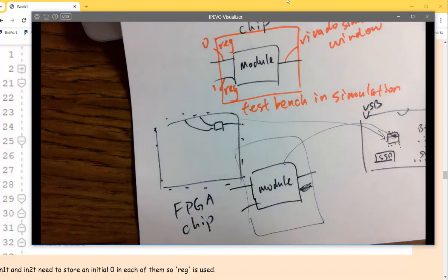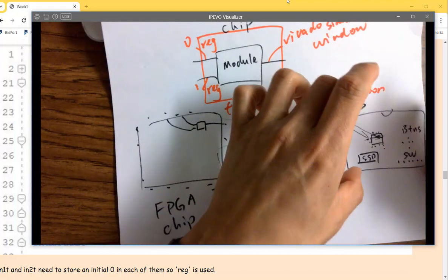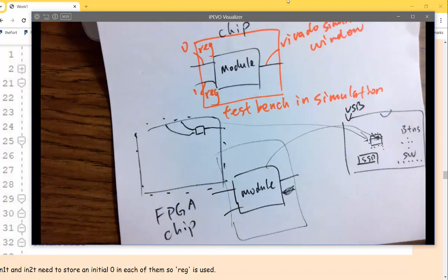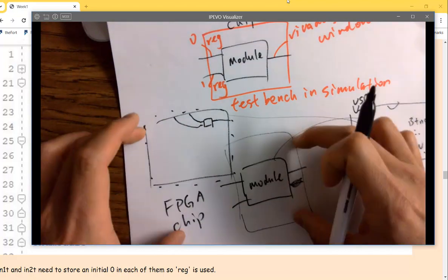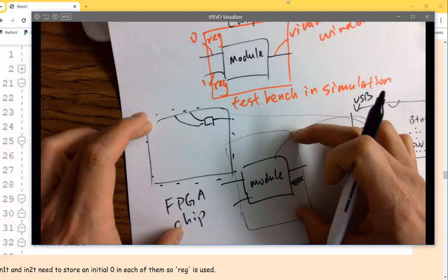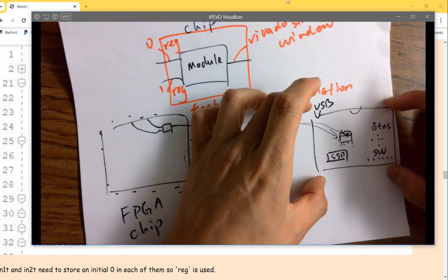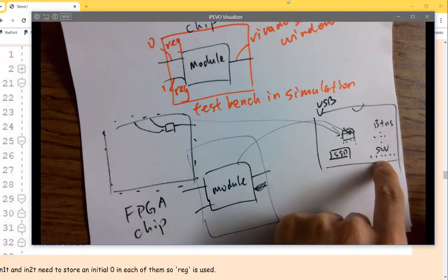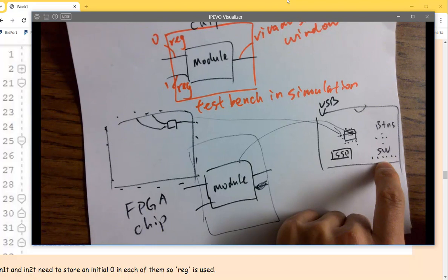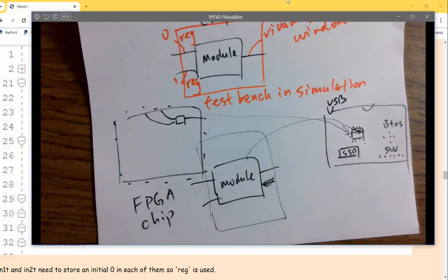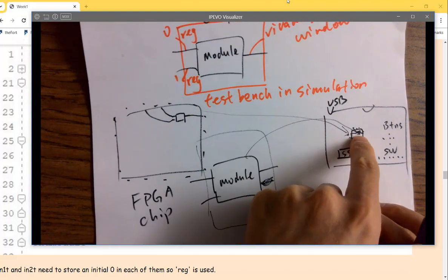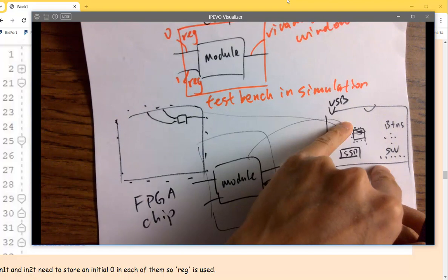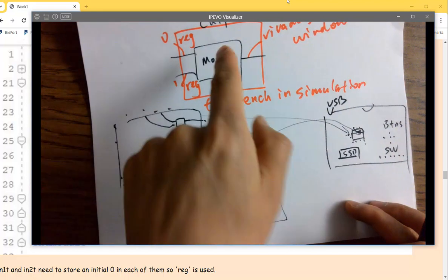So you are not looking at the simulation waveforms like what you saw in LTspice on your computer, but you are giving the input and looking at the output on the FPGA. Okay. So for this example, if you're using the FPGA as a test bench, and this FPGA you have, the Basys 3 board, okay? Could you let me know if switches are inputs or outputs? Inputs, so you are giving, like, the switch on and off to give 1s and 0s to your chip in the FPGA, right? You can make the connections by writing the Verilog to specify that, okay?